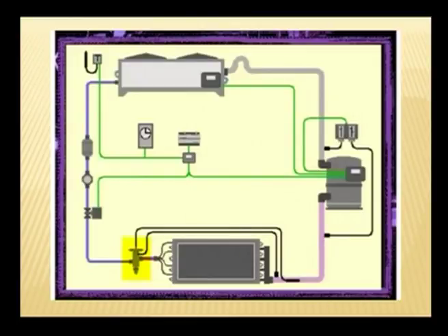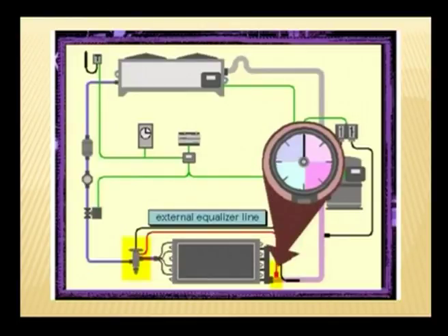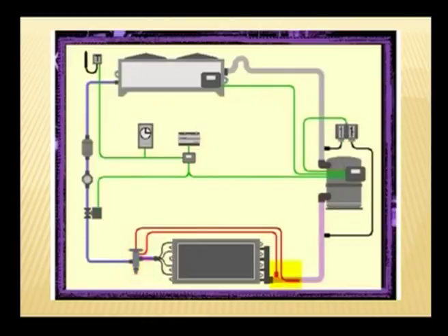You will notice that the expansion valve also receives a pressure signal, also measured at the evaporator outlet. This allows the expansion valve to adjust to the pressure drop in the refrigerant as it goes through the evaporator. The pressure drop lowers the evaporation temperature slightly and could give a false superheat reading if it were not compensated for. Under normal working conditions, the level of refrigerant stabilizes in the evaporator so that the flow of liquid is proportional to the amount of heat to be absorbed.